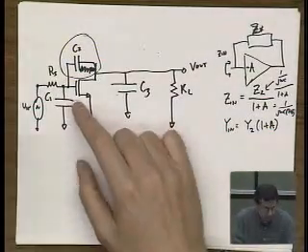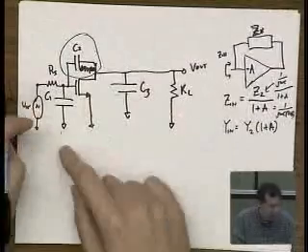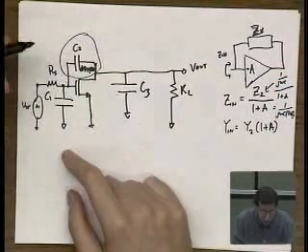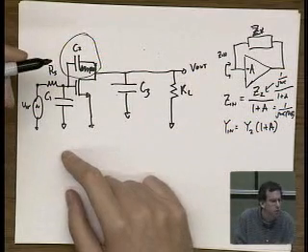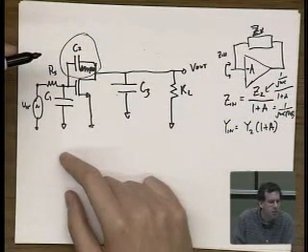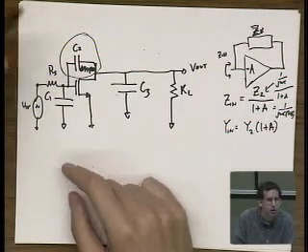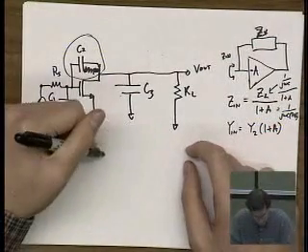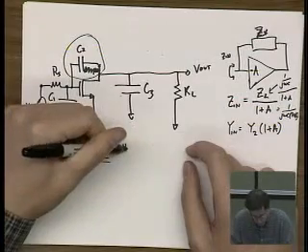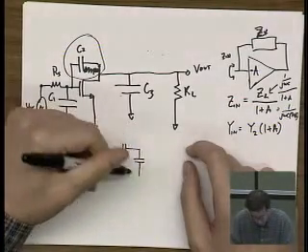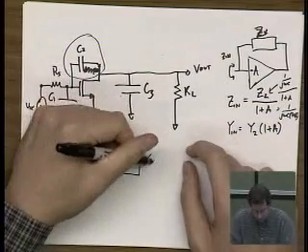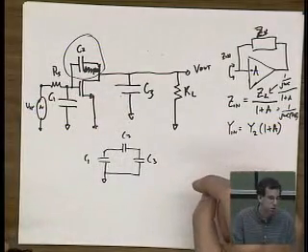So let's look at this. In this circuit, and I hope I'm not confusing you by talking about this, we've got 3 capacitors. So one could say, well, that means there should be 3 poles because each capacitor can have an independent voltage across it. That's not true, because if you just draw the capacitor network, you've got C1, C2, C3, right?